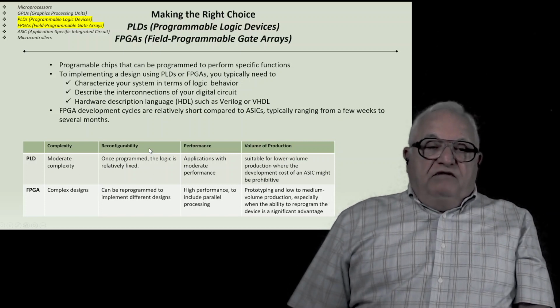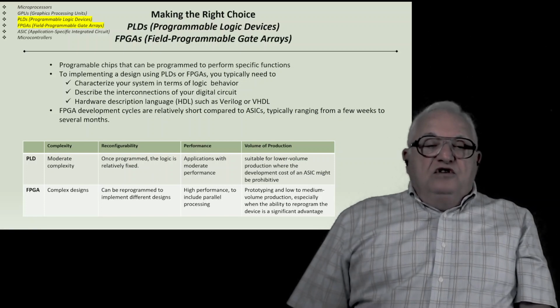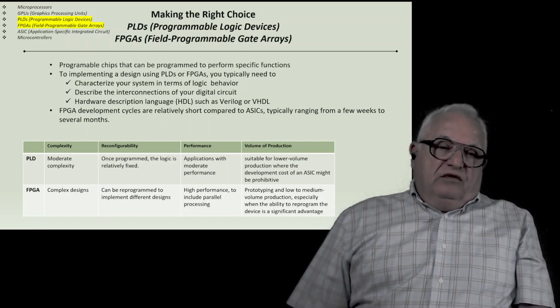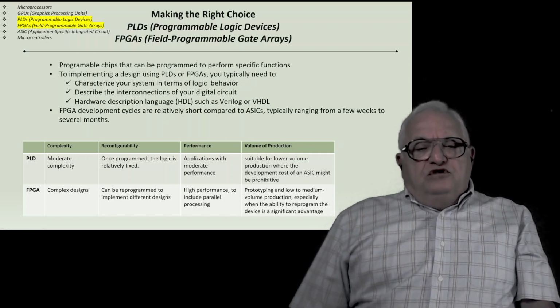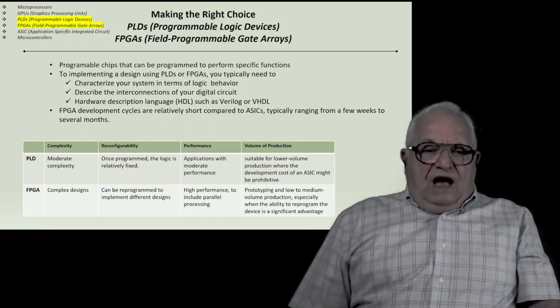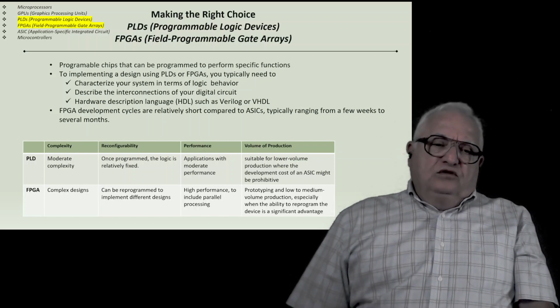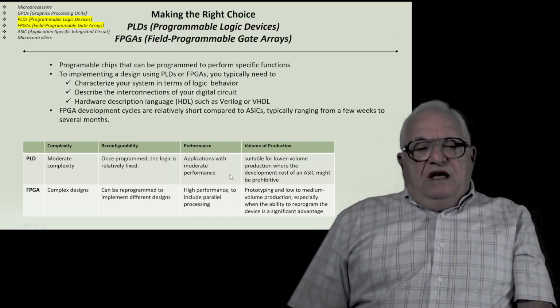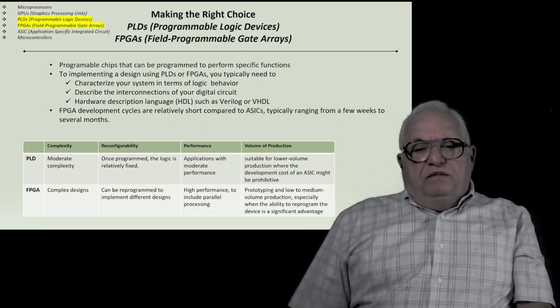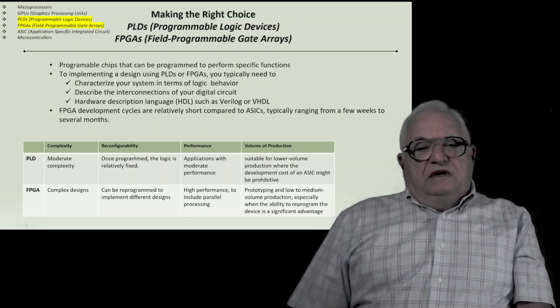For PLD reconfiguration, once you burn your logic into a PLD, you're really not thinking you're going to have to reprogram it. On the other hand, with FPGAs, once you program your logic, there are so many gates that you'll have the capability to add to the logic or remove some stuff and add others. That's due to the number of gates. Performance: FPGAs have better performance than PLDs. For volume production, FPGAs would usually be much higher volume than PLDs.